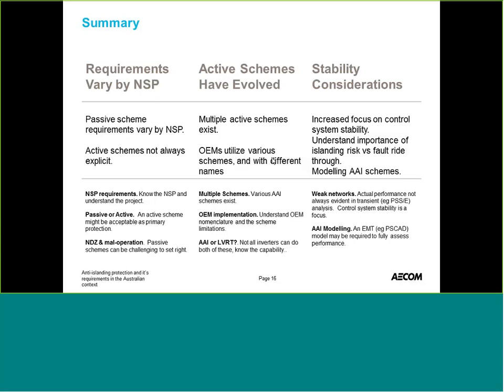And in that case, you really want to make sure that you've got your active anti-islanding scheme model, or the algorithm model, so as you do your analysis and look at various contingency events, you know that there's not going to be any adverse impacts. If there's going to be an island condition, the scheme will detect an island and disconnect, and also making sure that in contingency events, there aren't any instability issues as part of the control system.